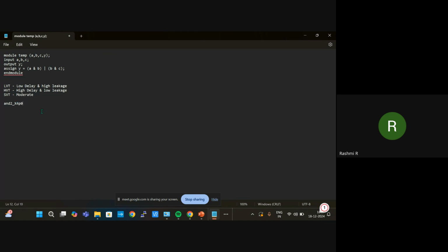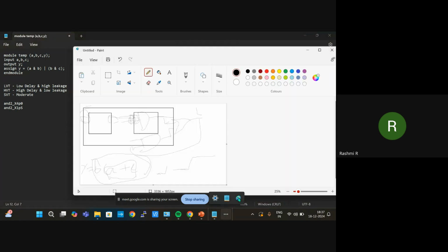Let us say 4P0. We will be having some cells like 0.5 drive strength also, 1P5, 4P0. Mostly these 0.5 cells and 1.5 cells will cause some DRC issues. So mostly we will go for 4.0, 6.0 drive strength, 4 drive strength only. This 4 represents the drive strength, the driving capability of a cell. Okay, got it?